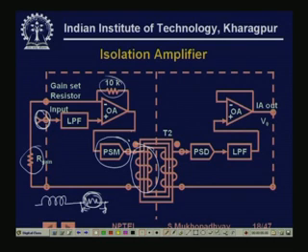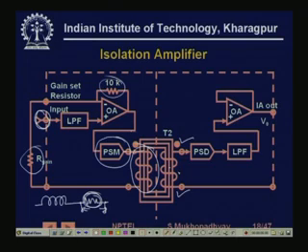As we shall know, in the secondary we will get the same wave, only by some turns ratio. But see that there is no electrical connection between the primary and the secondary. So therefore the secondary side grounds and reference potentials are completely different from the primary side ground.